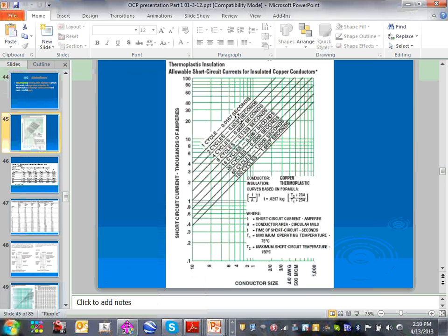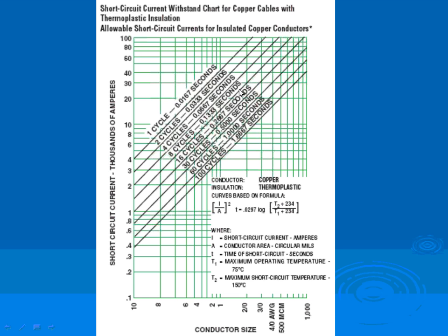So, all right, who cares? It doesn't happen often, guys, in our industry, but in the high voltage industry it's a big deal. The setting of the circuit breaker will determine the size of the conductor. In the low voltage industry, 600 volts or less, what determines the size of the conductor is the full load current of the equipment. Then you multiply by 1.25 if it's a continuous load, and size your conductor. In the high voltage industry, where short circuit is a decisive factor, you have to look at the short circuit too. Look how this can change easily.